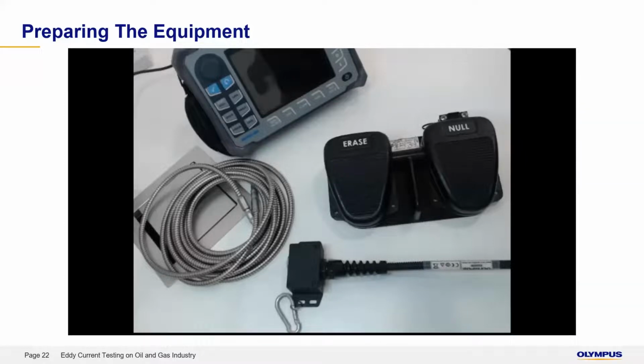Okay, thanks, Joshua. So for this second part of this webinar, I'll be using the Nortec 600D dual frequency and the HVAC heat exchanger tubing kit. Our HVAC heat exchanger kit comes with different adapters that cater to ECT, RFT, and NFT probes. It also comes with a 2-pedal foot switch for better workflow and a splitter to connect both probe and foot switch to the Nortec 600D.